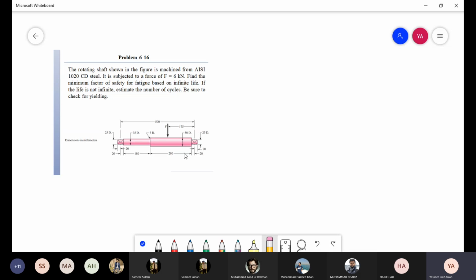So what should be the first step? We can discuss stresses first, or let us do the strength part first. Strength part is the easier part we have been doing. There are two parts to this question: one is the strength part, where you calculate the actual endurance limit of this shaft, and the other is the stress part. We will come to that later.